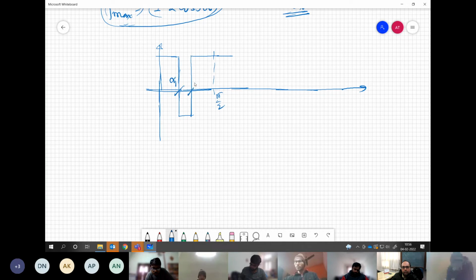Say alpha 1 and alpha 2. Of course, these levels are the same. Now I have 2 degrees of freedom in my pole voltage. So apart from maintaining the fundamental voltage, I should also be able to control any one harmonic, or maybe something better. You understand my point?